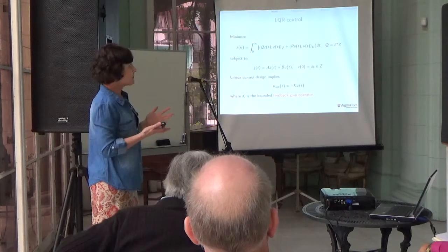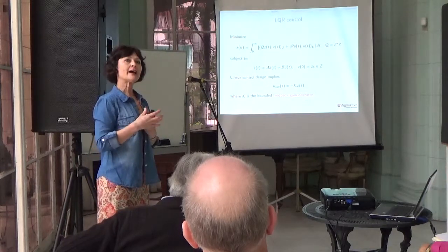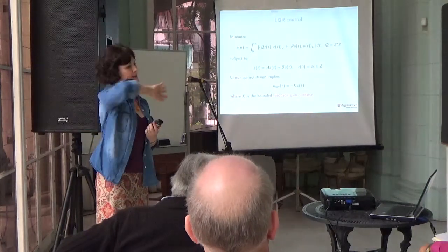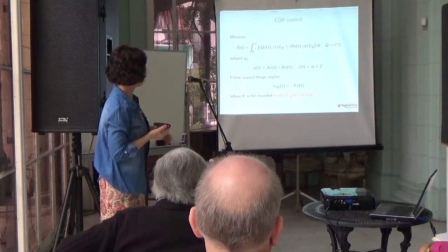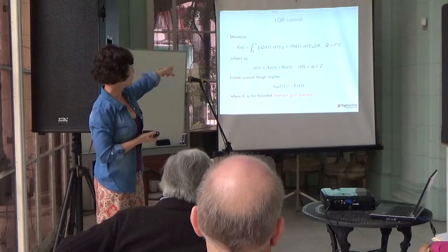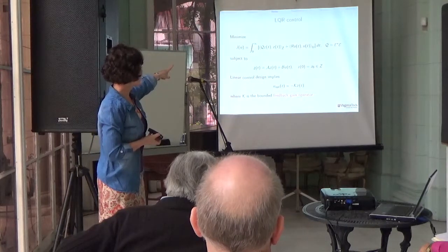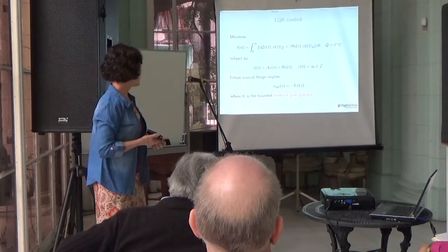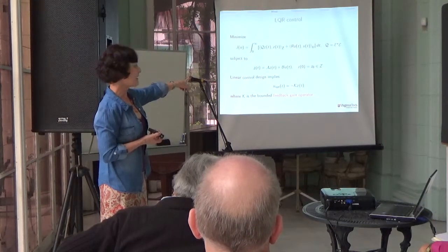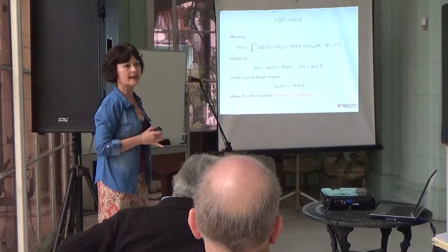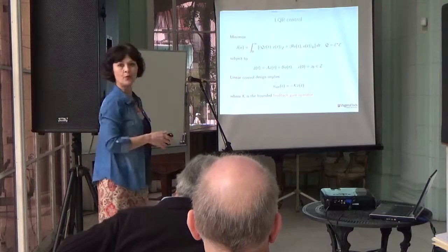So the problem then, if I use a linear quadratic regulator control, it alludes to the fact that I know the state, temperature, and velocity everywhere in this room, which we know is not true. So this is the perfect rule if I have it. So I want to minimize that quadratic cost function subject to a system of partial differential equations. And under very reasonable conditions, if that optimal control exists, it will be an operator, K, bounded feedback operator times the state. So you can see the feedback. It looks at the state and it will adjust the control accordingly.